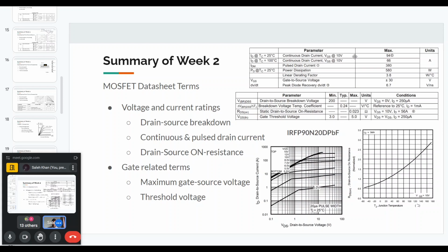And here, this also is given at a VGS of 10 volts. And so if you see in the data sheet, you will be provided with these curves, which are basically the output characteristics of the MOSFET in logarithmic scale. And if you see as the gate source voltage increases, we go from the blocking region through the active region to the linear region or the ohmic region. And the ohmic region is where we want to operate the device.